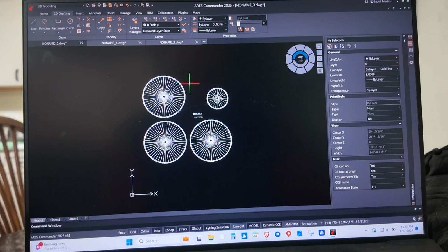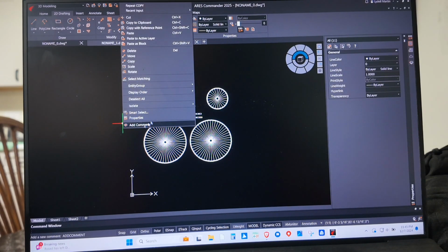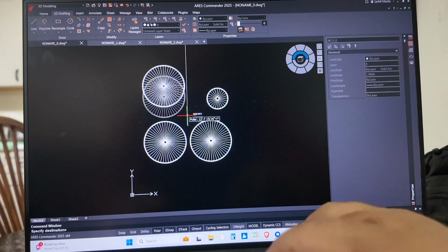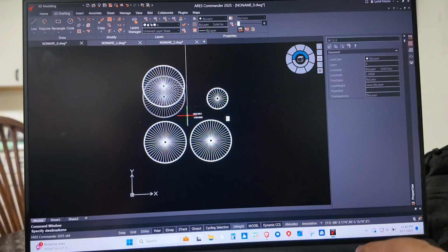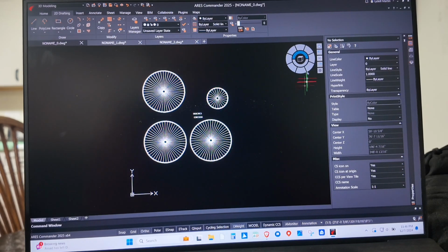Actually, we don't want this bin here, because if we would ever want to do that, we would want more room. We're going to move this bin 6 foot, because if we ever wanted to run a reclaim down through here, we need 12 foot in between here if we ever wanted to run a reclaim down through. So we have our 2 elevators here. We have our bin here,